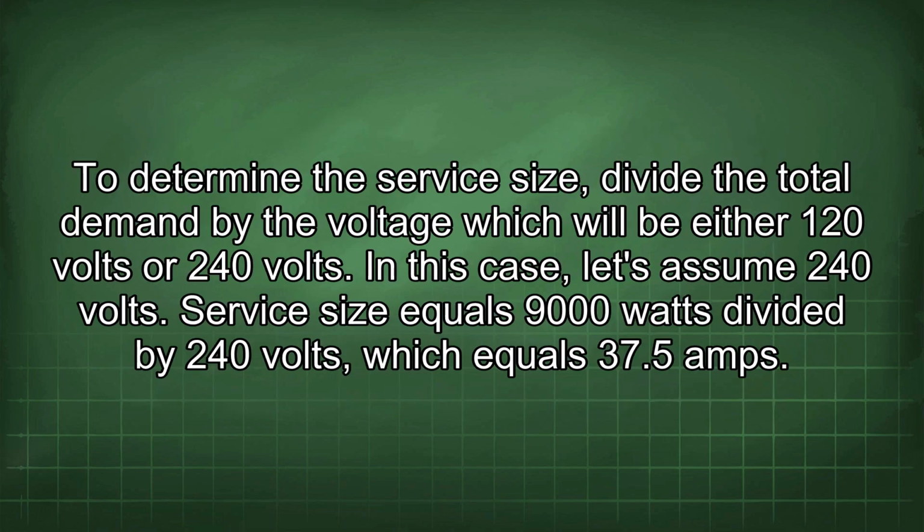To determine the service size, divide the total demand by the voltage, which will be either 120 volts or 240 volts. In this case, let's assume 240 volts. Service size equals 9000 watts divided by 240 volts, which equals 37.5 amps.